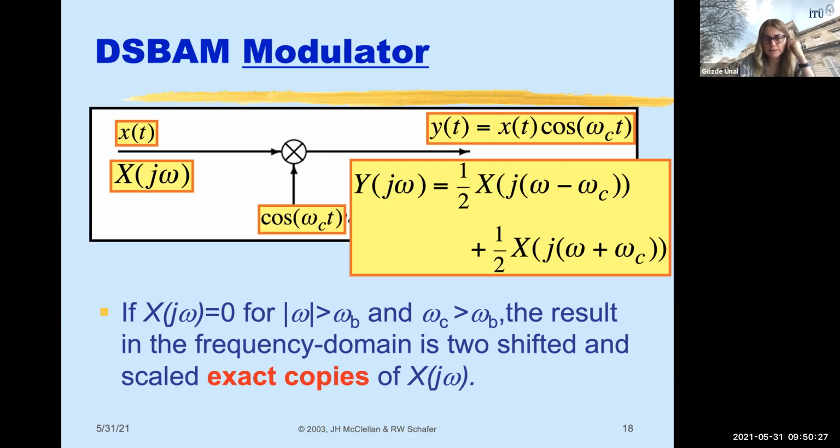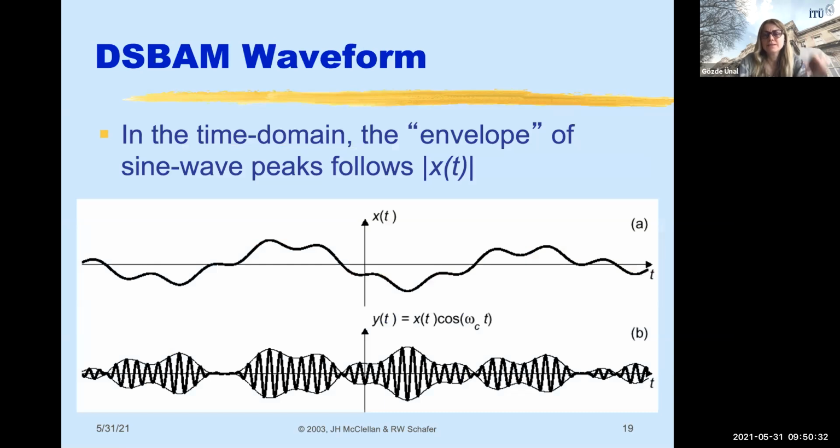But before that, we've already said this, two exact copies. This is showing the modulated signal in the time domain, guys. Y of t is x of t times the carrier signal, cosine omega c t. So let's say this was the input signal to be modulated and transmitted. Amplitude modulation is a telecommunications application of Fourier transform. And the modulated signal you see is this envelope. This is an AM signal, by the way, AM radio waves.